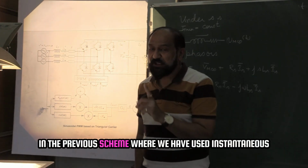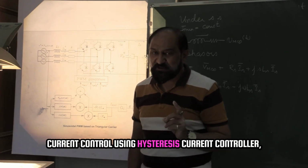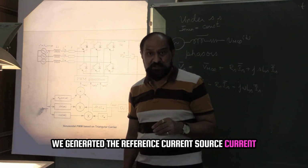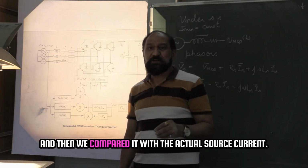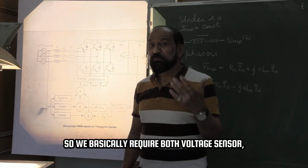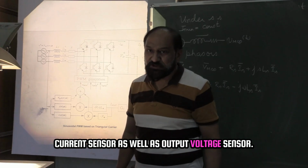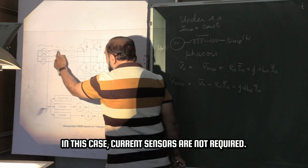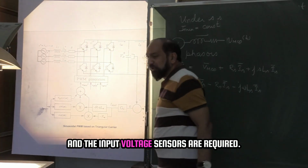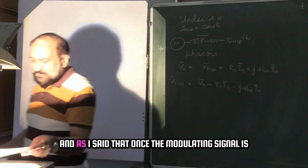In the previous scheme, where we used instantaneous current control using a hysteresis current controller, we generated the reference source current and then compared it with the actual source current. So we basically required the voltage sensor, the current sensor, as well as the output voltage sensor. In this case, current sensors are not required, only the output voltage and the input voltage sensors are required.